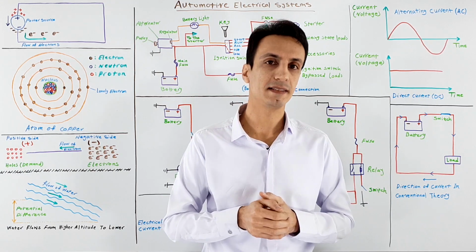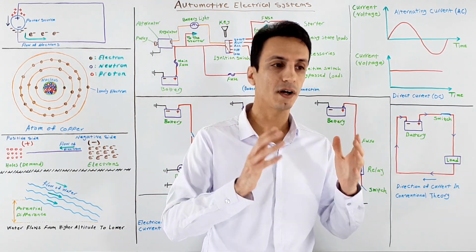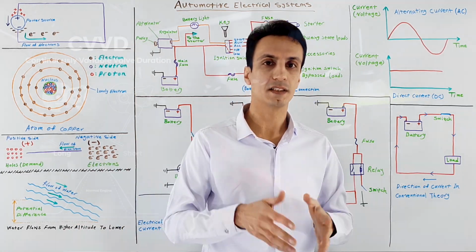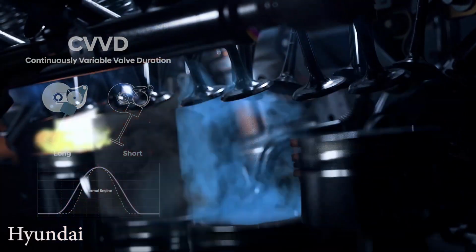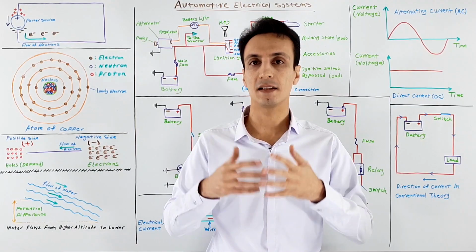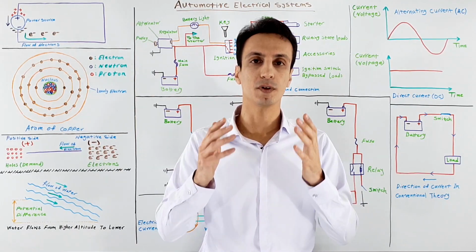Now, you can release the ignition key and it returns to the run position and the starter disengages from the flywheel or flex plate. But the engine continues to run as long as the ECM receives crankshaft rotation signals and enough air, fuel, and sparks are provided.